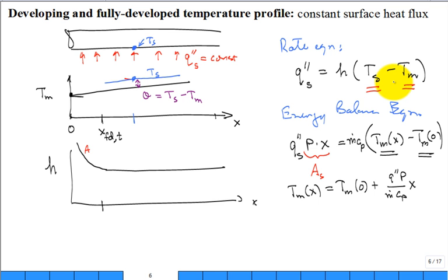So now we know that in the entrance region, this is up to being fully developed both thermally and hydrodynamically. I'm going to put the Prandtl number to 1 and it'll develop at the same rate. So this is the entrance region. Now what I'd like to talk about is what that surface temperature of the wall does. We already talked about the bulk or the mean temperature of the fluid, right? So does this come in and go pretty close to it, or does it stay flat, or does it go like this? So answer A, B, or C. I'm sorry, I think you see what I'm trying to show.